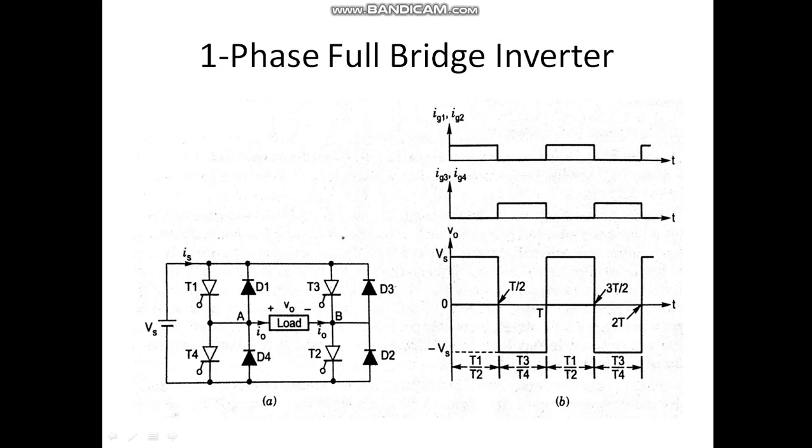In the single phase full bridge inverter, again when the load is resistive, these black ones are diodes, which are of no use. Only two limbs with the four devices, four thyristors, will be of use. Now I will go a bit quickly because you have gone through the concept, so now it will be very easy for you to understand.